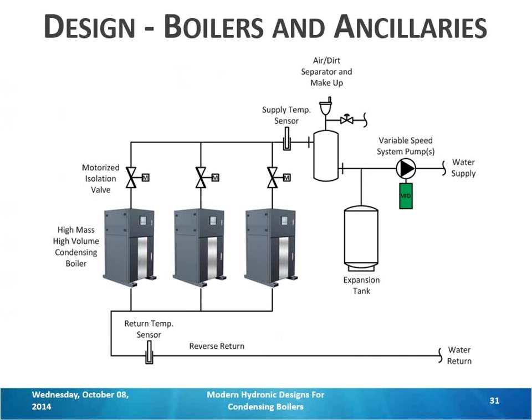And we expand that out to the entire hydronic system. We have multiple zones with modulating valves to control the flow through those zones. We have a bypass at the furthest point in the system, so if these close down too far, we can crack this bypass open and maintain a flow through the system to monitor temperatures and prevent that pump from deadheading.